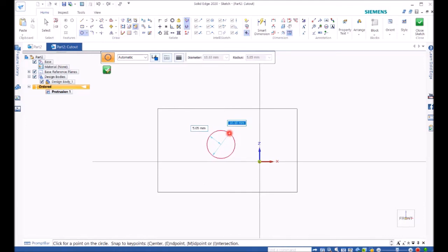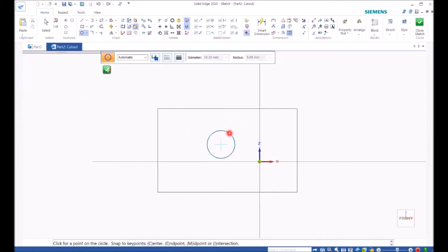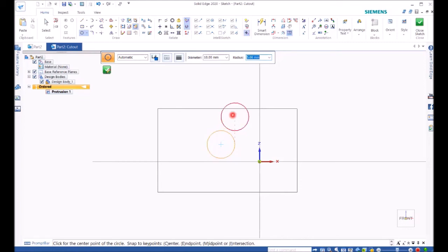It looks okay, and then you can enter the dimension. For example, I put a 10 here, press return, it's fixed. If you hold the mouse again and move it slightly, don't hold the key down, you can see a second circle come out. This is just a continuation of the first one. In order to terminate that one, you need to right click the mouse button.